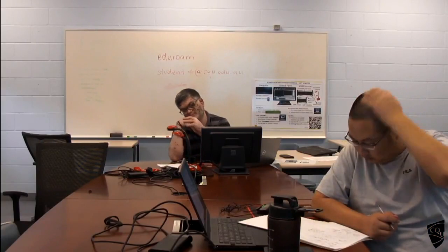When I measure from here, the distance is d by 2. When you measure from here, it is y UC minus d by 2. This distance you need to provide. So the yi is different, but if you put the values in that equation, both will give the same answer.